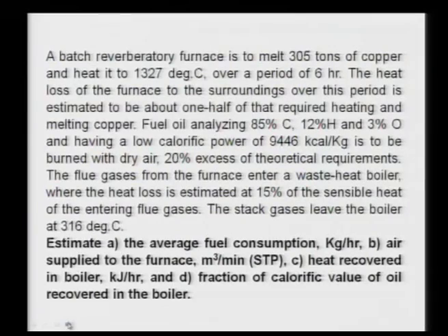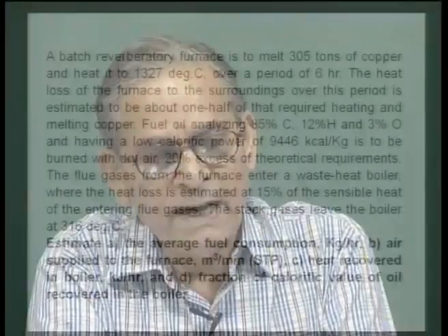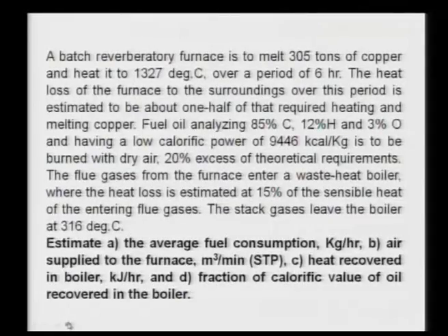So, the heat losses are also given, but in a different form. It is said that whatever amount of heat you require to heat copper from 25 degrees Celsius to its 1327 degrees Celsius, half of that will be the heat loss to the surrounding. Fuel oil analyzing 85% carbon, 12% hydrogen and 3% oxygen, and having a low calorific power of 9446 kilocalorie per kg is to be burned with dry air, 20% excess of theoretical requirements.